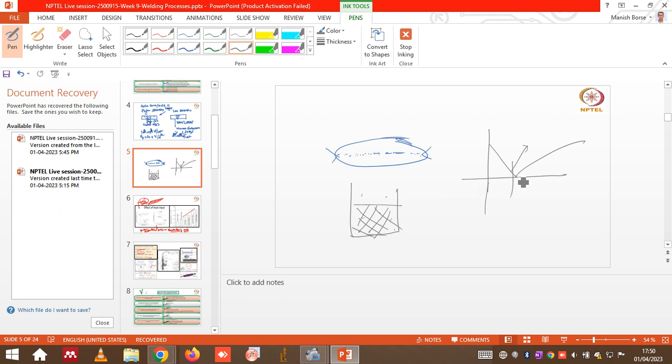Okay, so in such alloys, let's say there are secondary phases that will form at a much lower temperature than the melting point. So there is a very narrow difference between the solidus and liquidus lines. So this kind of composition doesn't have any problem in such a case. But alloys which have a composition far from the eutectic have a very wide solidification range, right?